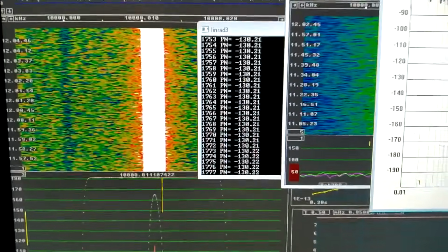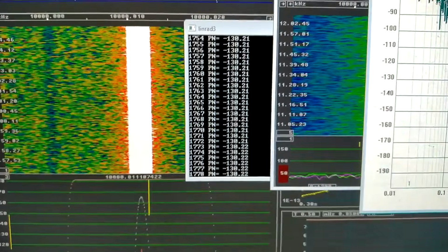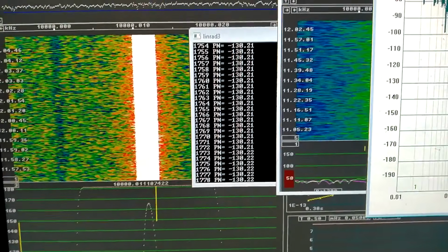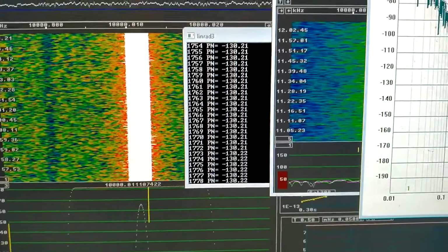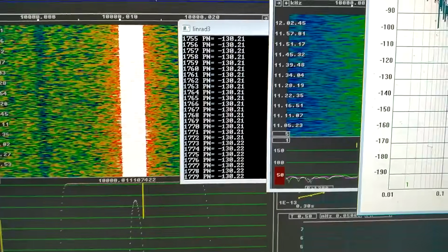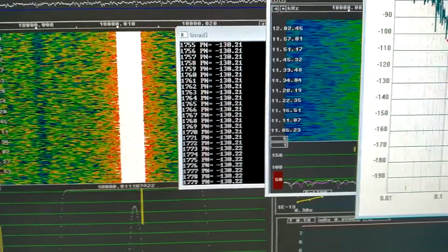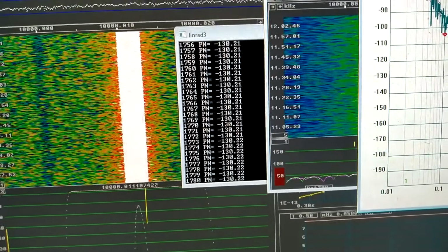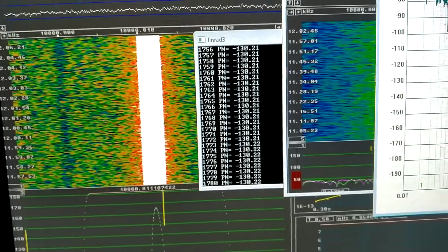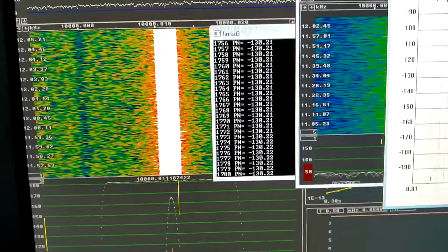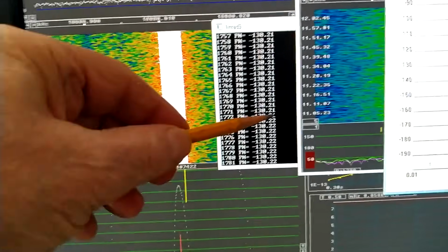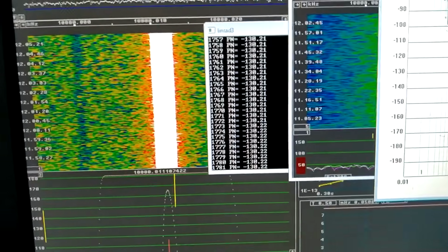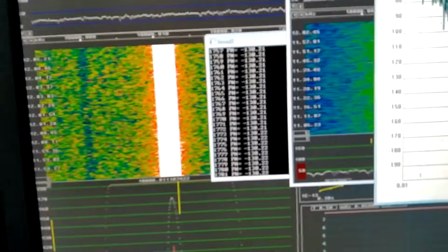So I decided this must be caused by the crystals. And then I thought maybe I could try to force them to age faster by increasing the power. I increased the current from nominal 1 milliamp to 2 milliamps, and that increased the average noise significantly, it went down to minus 125.